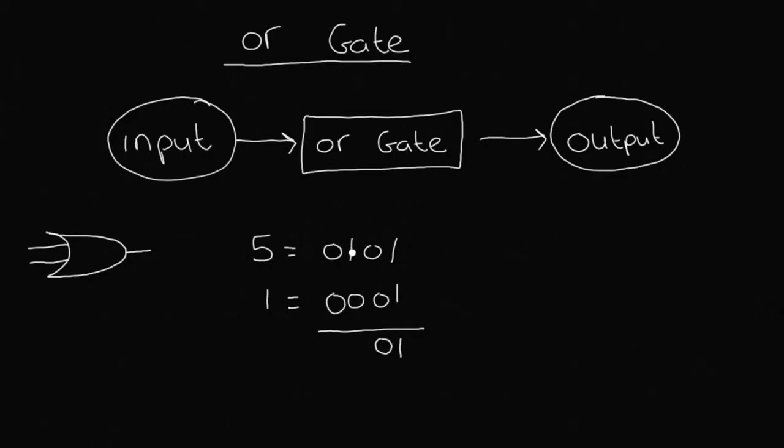Then when we look at the third column, we've got 1, 0. Again, once we've got a 1, we can bring it down because this is an OR gate. If it were an AND gate, it would be a little bit different. And again here we can see 2 zeros, so 2 zeros would give us an output of 0. And if you look at this number here, you'll see that it is equal to 5.